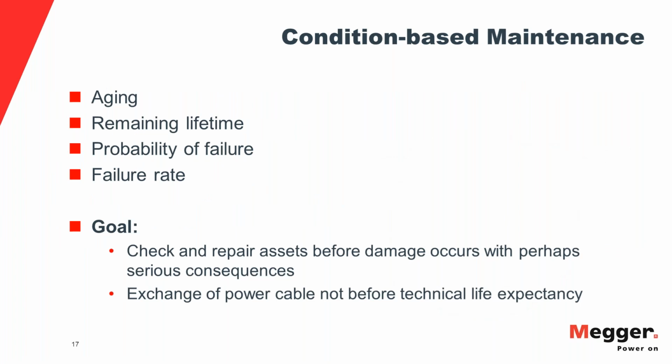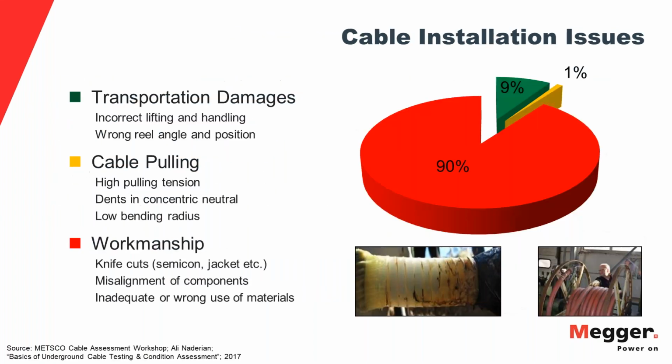So then back to condition-based maintenance. For condition-based maintenance, again, you want to overall increase your reliability, and particularly for PD measurement. So what is really the benefit of this? Instead of just doing VLF testing, also putting PD measurement as the number 2 test there. So first of all, you are able to check and repair the assets, and back to here and to here.